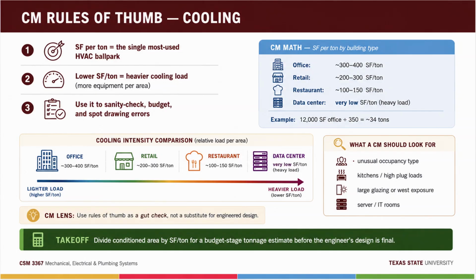People first. Every human body is a little furnace running around the clock at roughly 98.6, dumping heat into the room, and dumping it in both flavors. Sensible heat off your skin, warming the air. Latent heat in your breath and your sweat, loading the air with moisture. The slide's planning numbers for a seated, office-type occupant: on the order of 250 BTUs per hour sensible and 200 BTUs per hour latent. Roughly 450 BTUs per hour total per person.